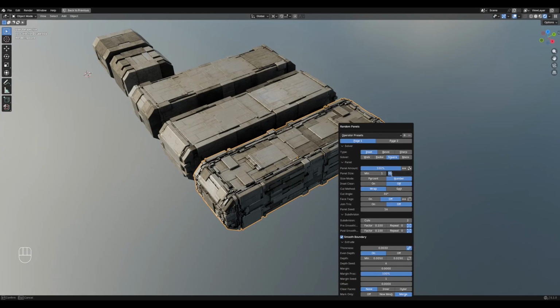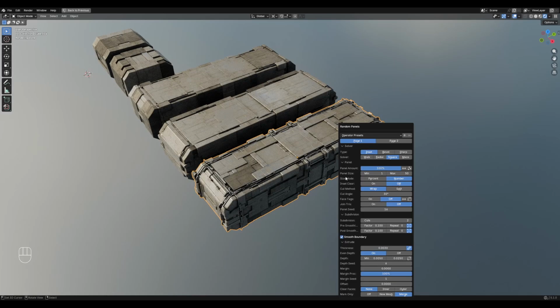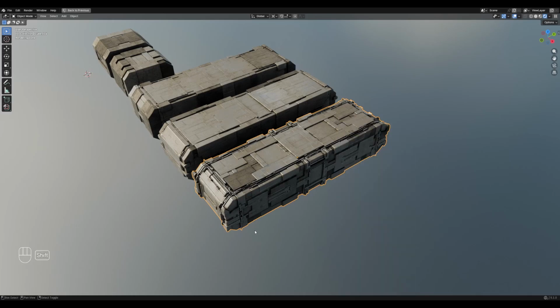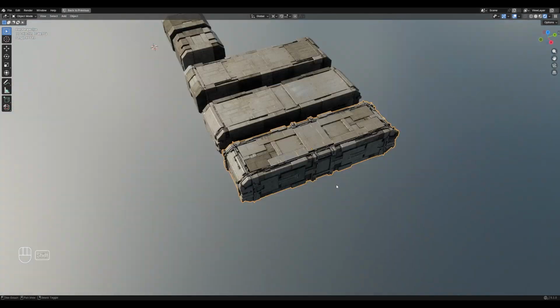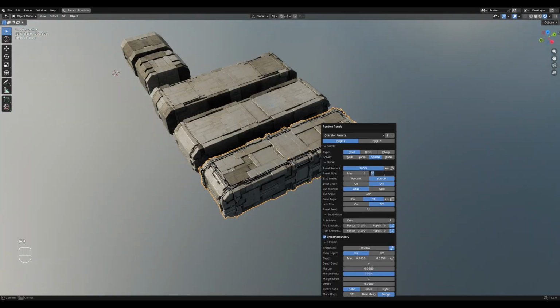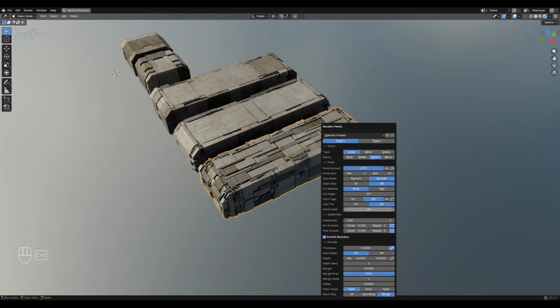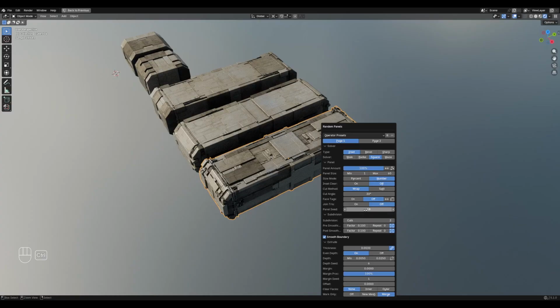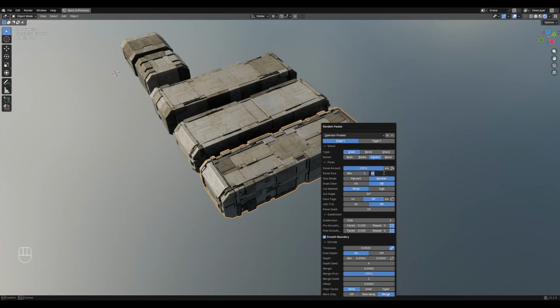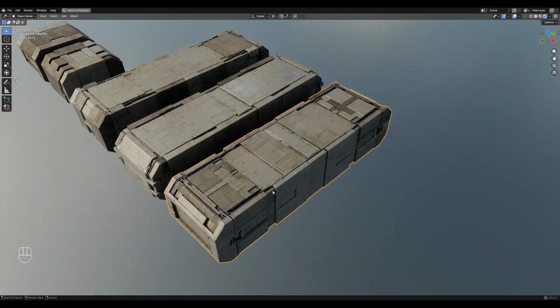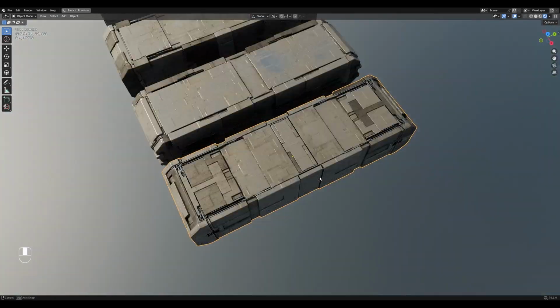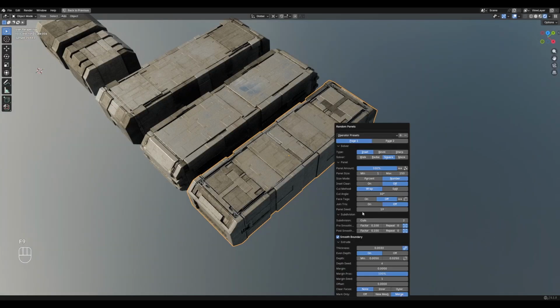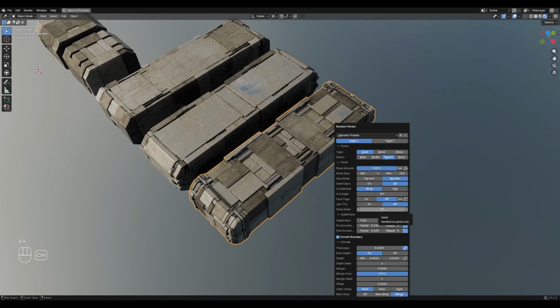Set the panel size to 1. We can set the maximum panel size to something like 50. So with this combination, it will generate small details as well as areas that are more relaxed, and just play around with the panel seed. So let's use something like 150. So it gives us really relaxed areas with areas that are also very detailed.